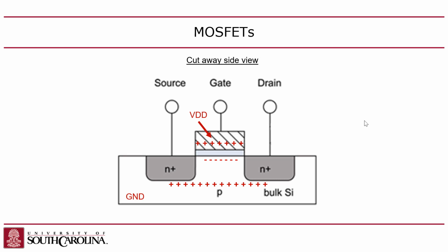And that creates a capacitor because in between the gate and the substrate is a little glass, silicon dioxide. So you put a positive voltage here, and that'll create a positive charge. That'll charge the capacitor.